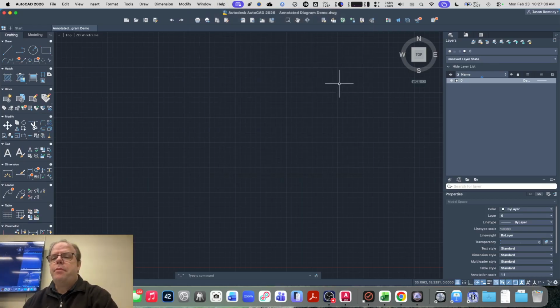Okay. So every AutoCAD drawing comes with a layer 0. And so far, like on that first project, I just had you draw on layer 0. But drawing on layer 0 is considered bad form for a couple of reasons. The main reason is that every AutoCAD drawing has a layer 0, and part of the point of layers is to group things together so that you can style them, affect them, or process them together.